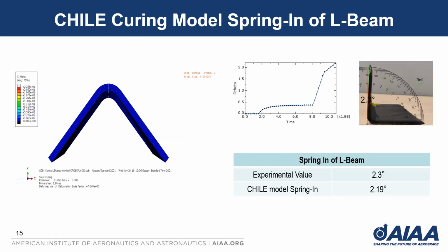properties. Finally, we use a Python script to obtain the spring-in based on the residual stress and deformation from the curing model. Here we see the spring-in response of the L-beam as time increases during the curing cycle. The spring-in gradually increases and reaches maximum during curing. The results obtained from our curing model are in close comparison with the experimental results.